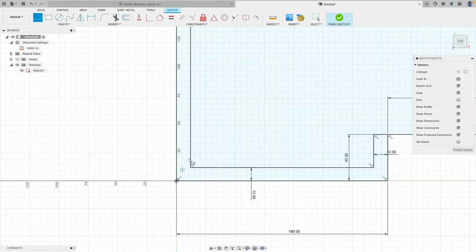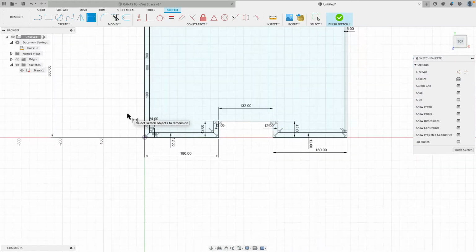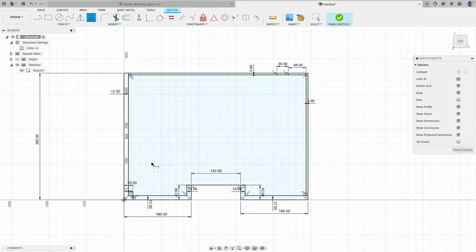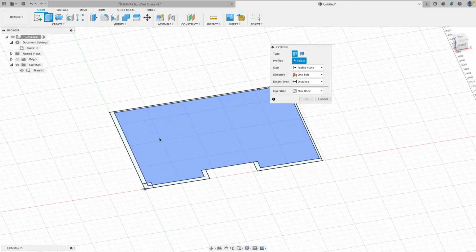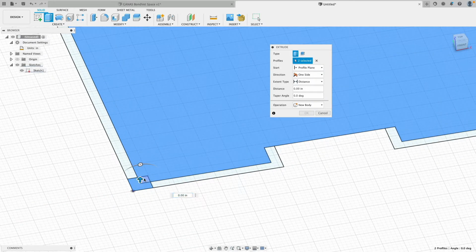Then I will also down here create a line, horizontal and vertical. I will make these 2 lines equal. And then one line here I set to 24. Very good. That's actually for the vertical post. Good. This post we also have here and here. I simply do not put this into the sketch because I can copy and paste the object. Very nice. Cool.